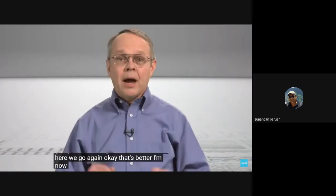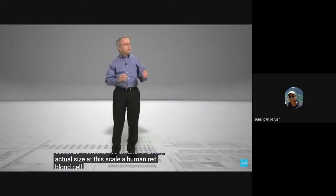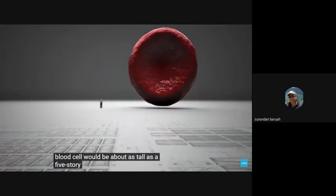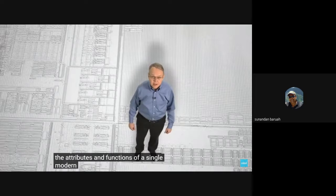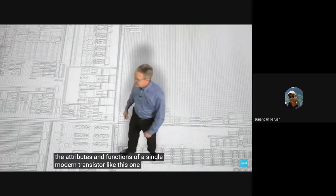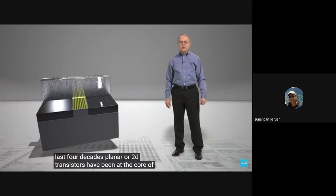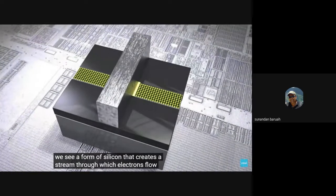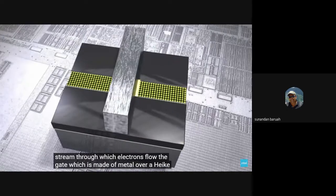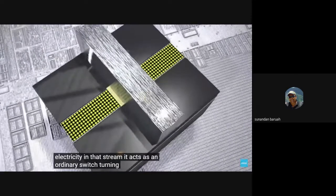Okay, that's better. I'm now approximately 100 nanometers tall, or about 20 million times smaller than my actual size. At this scale, a human red blood cell would be about as tall as a 5-story building, and I would be just the right size to demonstrate some of the attributes and functions of a single modern transistor, like this one. For the last 4 decades, planar or 2D transistors have been at the core of transistor design and architecture. Here, we see a form of silicon that creates a stream through which electrons flow. The gate, which is made of metal over a high-K insulator, controls the flow of electricity in that stream. It acts as an ordinary switch, turning flow on and off.